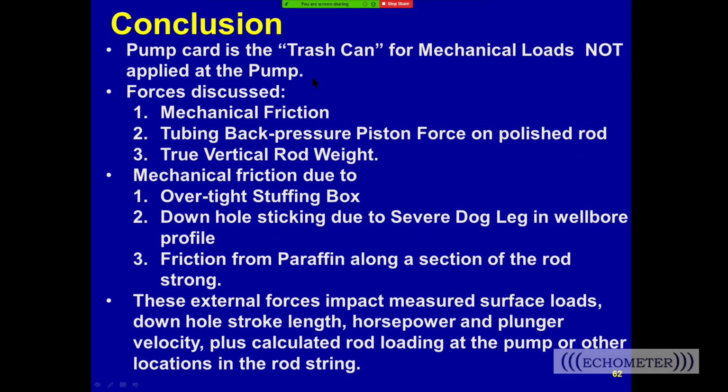So this is the ending slide here. The pump card represents the load that the pump applies at the bottom of the rod string. But if there's other mechanical forces applied along the rod string from the surface down to the pump, the wave equation doesn't typically know how to remove those forces, and they end up at the pump, and the pump becomes their trash can for unaccounted for forces.